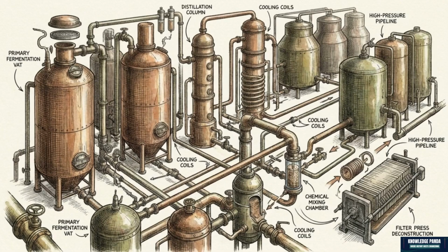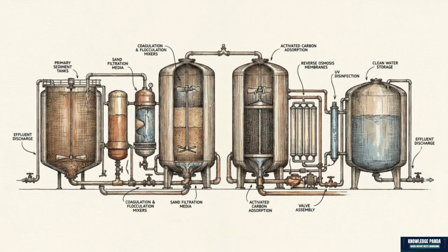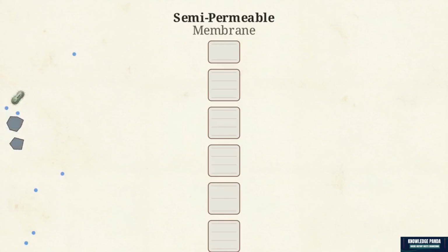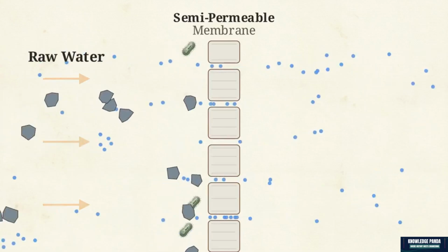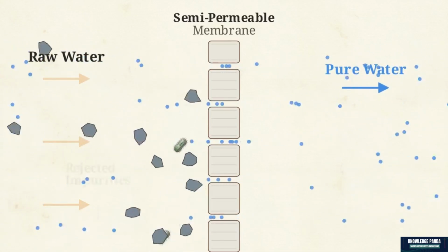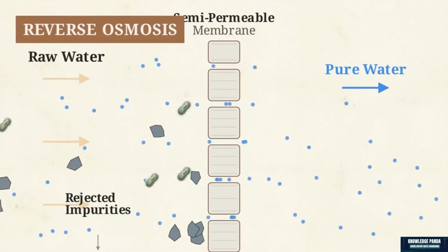Scaling up a consumable requires the rigorous application of fluid mechanics, thermodynamics, and solid-state engineering to guarantee the product matches strict human biological thresholds. The continuous flow liquid pipeline begins with massive-scale industrial water purification. This diagram shows a microscopic cross-section of a semi-permeable membrane. High pressure forces raw water against this barrier, allowing small water molecules to pass through while physically stripping out dissolved salts and chemical impurities in a process known as reverse osmosis.